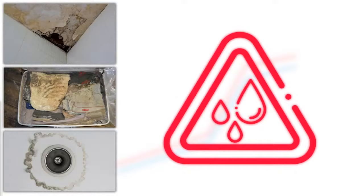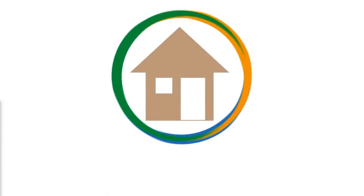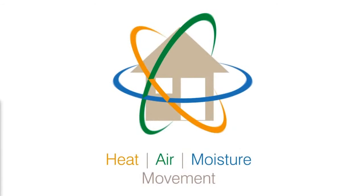Cold spots in the building, either from poor insulation, cold bridging or drafts, can also cause condensation in the living spaces, and this in turn leads to mould growth, which can have an adverse effect on the health of the occupants. Taking these factors together, it's very important that the management of heat, air and moisture in the building is carefully balanced, and the impacts of these are closely interrelated.